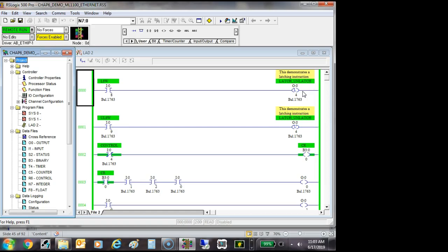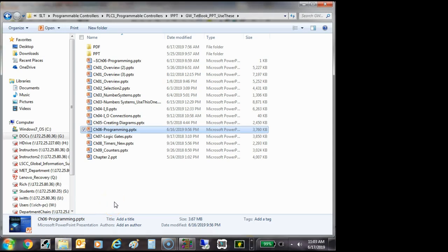So latch, unlatch, latch, latch. So notice I'm using a momentary contact. Of course, once it's latched, you can't latch it anymore. So this switch over here could go true 1,000 times and it's not going to change the state because it's latched, right? And then when I'm ready for whatever it's controlling to go false, then I use the circuit that has the unlatch circuit. And we use this a lot.